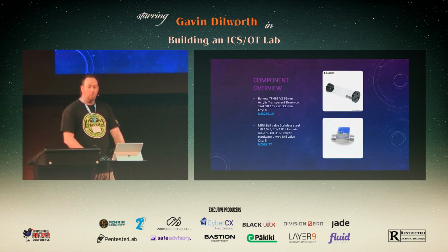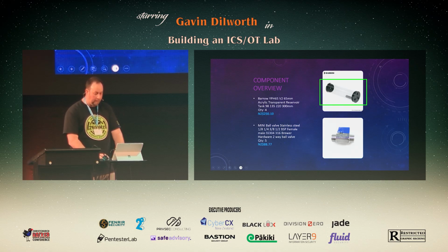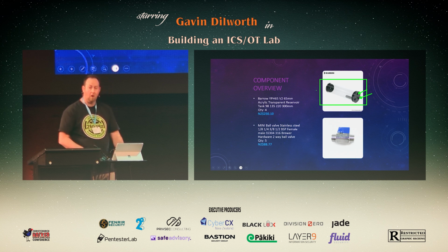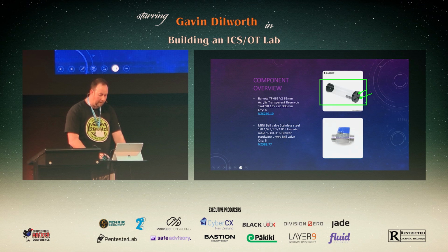For those wondering what the tanks are made of, that is literally water cooling for CPUs. So there's a great benefit for this. It comes with threaded inserts so that you can twist in some of the fittings for the piping straight away. Once that's twisted in, it's pretty watertight. And you've got the options of 3 at the top, which is good, so air can escape as water fills it up. And then I can have a manual fill or an automatic fill.